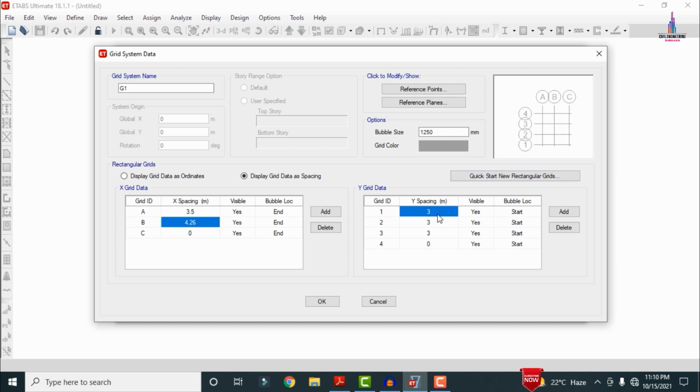Like this. After that, in the same process, we have to change the vertical distance. So here I am selecting the vertical distance. The first grid will be 3.4 and the second grid will be approximately 3.5 here. Okay, so here I am selecting 3.5 for the second value. Again, in the same process we have to consider the third value, which is 6.17.